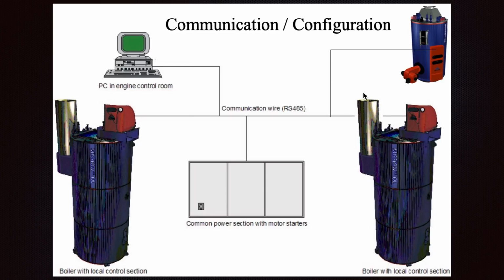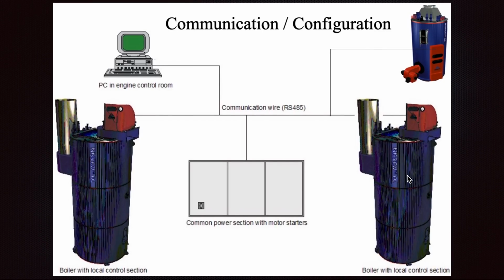In new vessels there is some design where there is a composite boiler with generator gases passing through, and in port we use that boiler. But in the big VLCCs, the big tankers, and probably the Suezmax, there is one auxiliary boiler running as a composite boiler, so you will always have steam in the port.